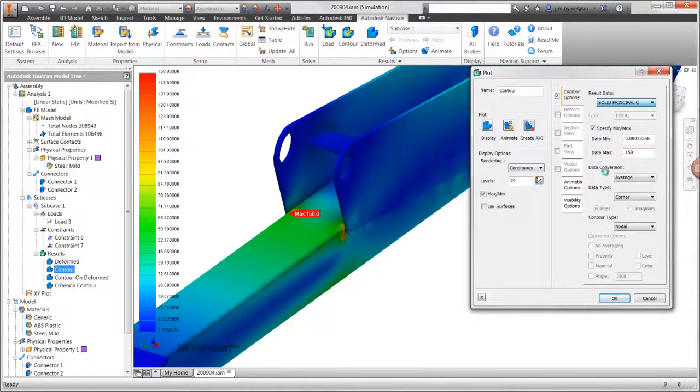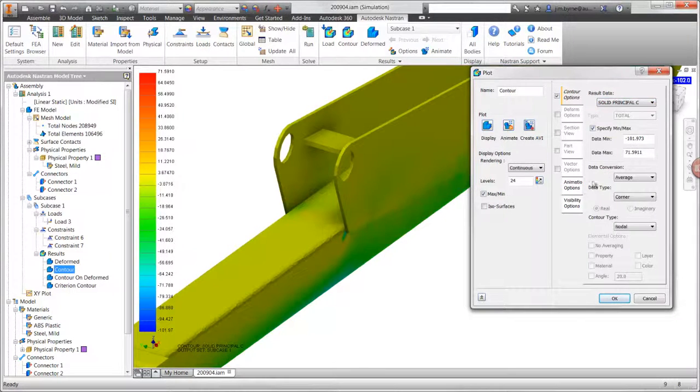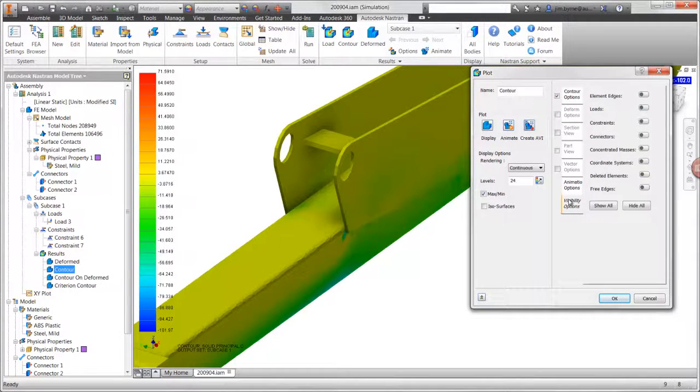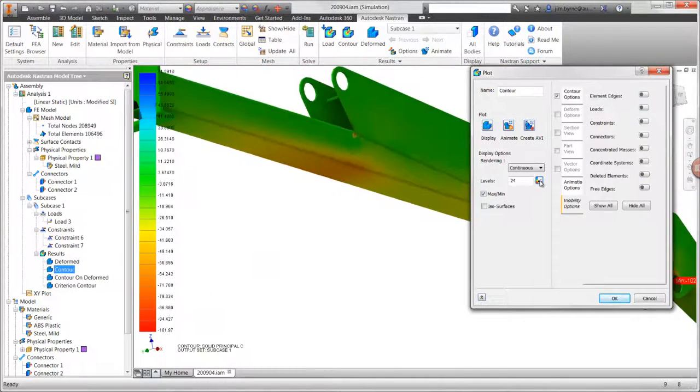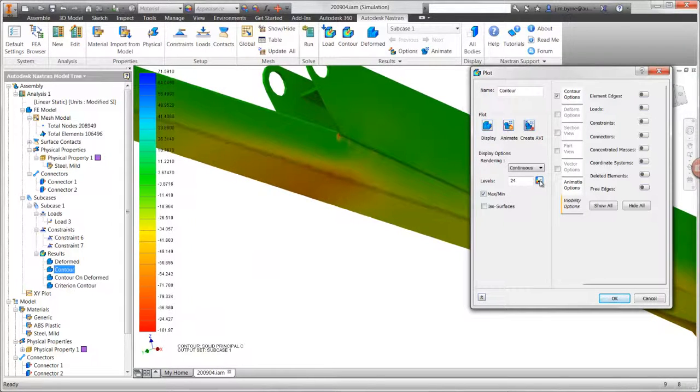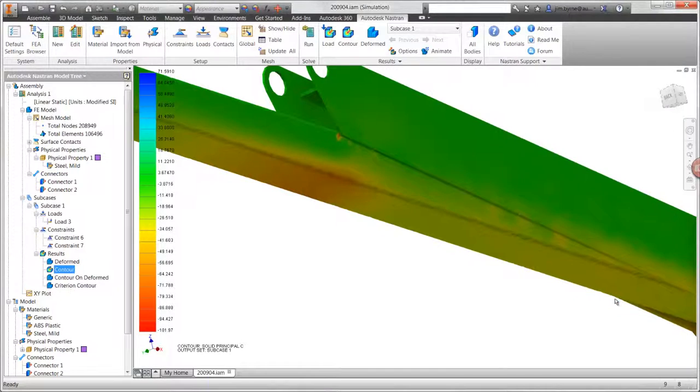There are also principal stress plots for focusing on tension or compression on the model. Let's have a look at compression. Underneath the steel tubing, we can see we have almost 100 megapascals of compressive stress. The material won't yield here, but it might cause a buckling failure.